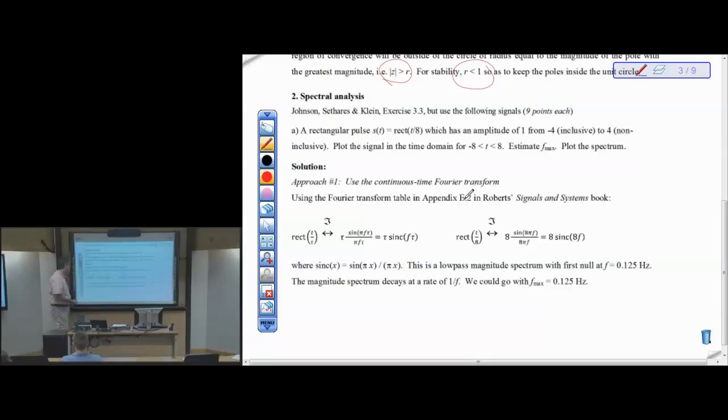So I give you a rectangular pulse. It's of width 8 seconds. It goes from -4 to 4 in extent. I know this can't run out of ink, but somehow it's running out of sensitivity. Okay, so here's our pulse shape, amplitude 1. I know it's operator error, I know. Okay, so 8 seconds in duration, and the null-to-null bandwidth in the frequency domain is 1 over this